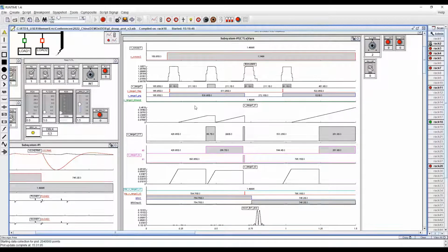The controllable source this time generates a series of voltage disturbances. Each of them has a duration less than the required minimum ride-through time. The duration between two consecutive disturbances is made greater than the required minimum time between successive disturbance sets, which is set to 0.2 seconds.